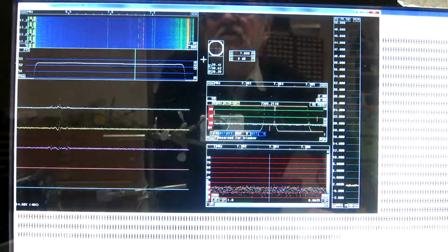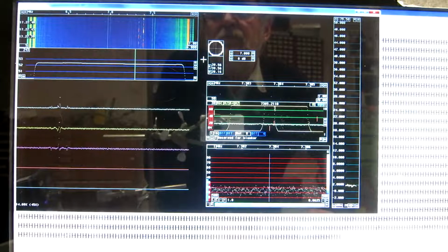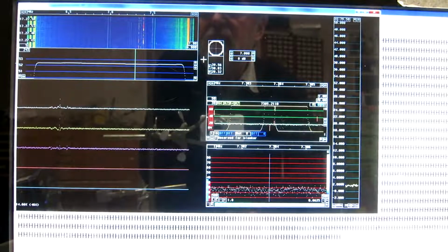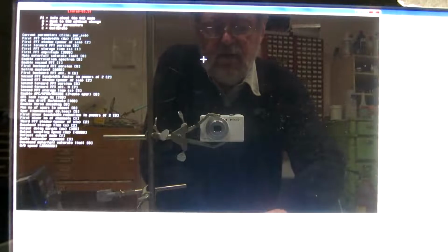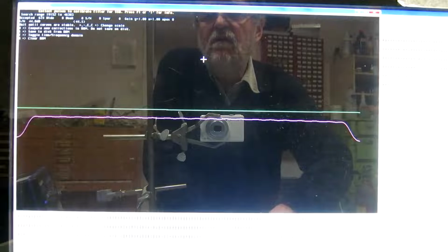If you are on VHF or microwaves with a very well-defined frequency response set by converters that are in front of the receiver, you might want to calibrate a little bit differently. I will show that. That would be X and calibrate and B and enter. And now first clear away the old calibration, collect the data,